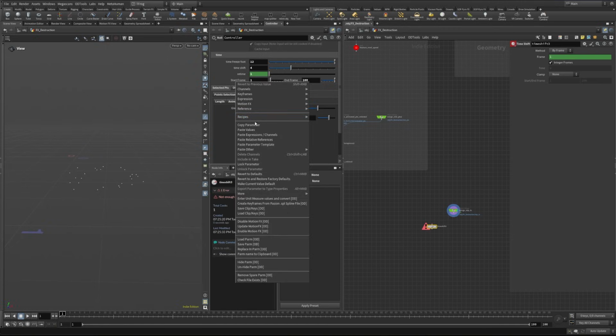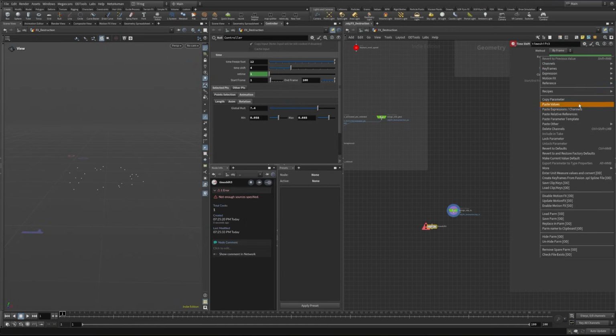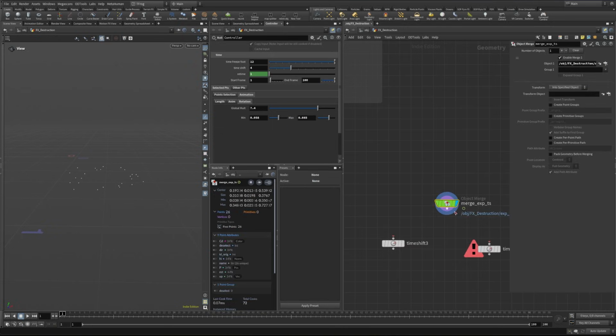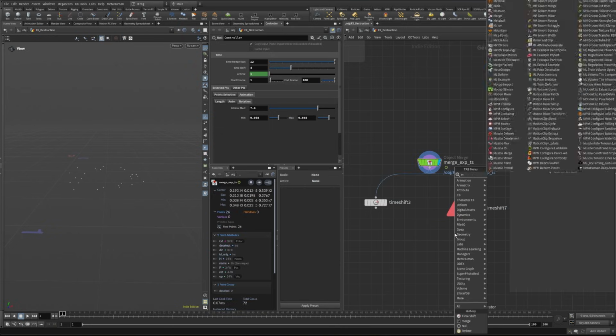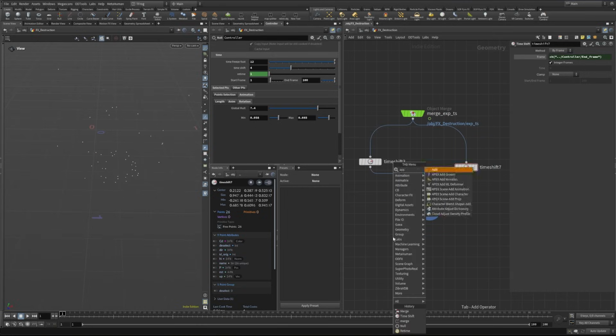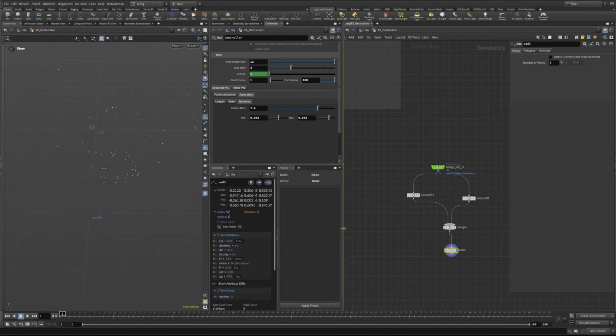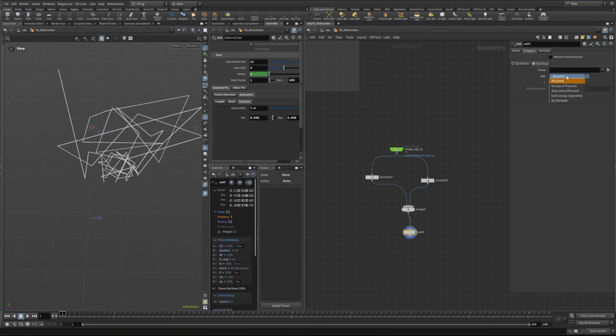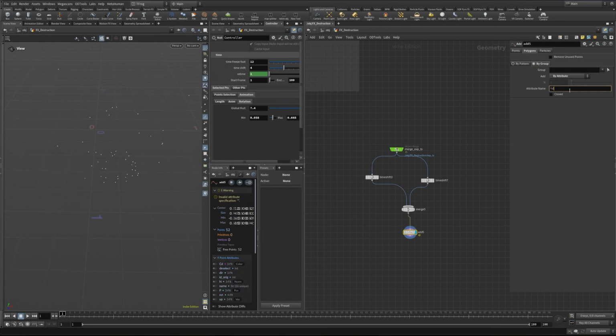And let's copy in our start frame inside this one. And let's paste this over. And inside here, we're using our end frame. Let's use this inside here and merge them together. So we got this points and this points. And with one add node over here, we'll give it a little bit more space. We can go to polygons, by group, by attribute, and we're typing ID orig or ID original attribute, and we're